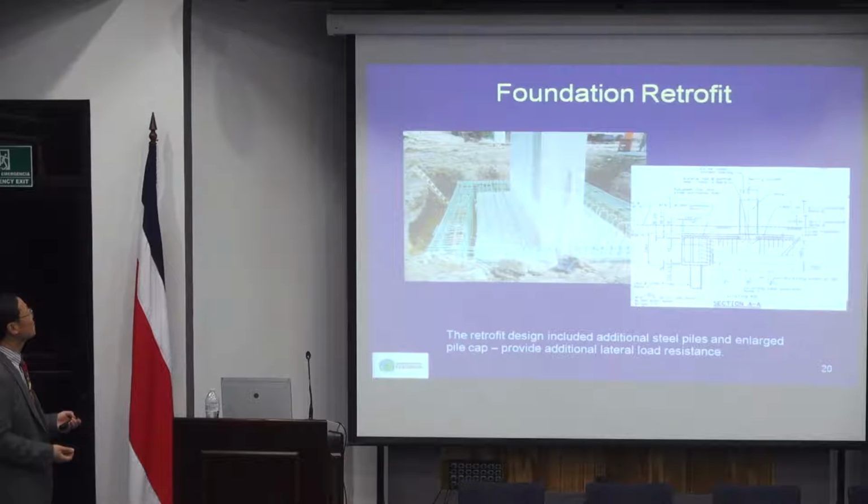So to fix that, typically we provide micropiles. We add additional micropiles and build a monolithic concrete new pile cap, so that you build a much larger footing for the piers.